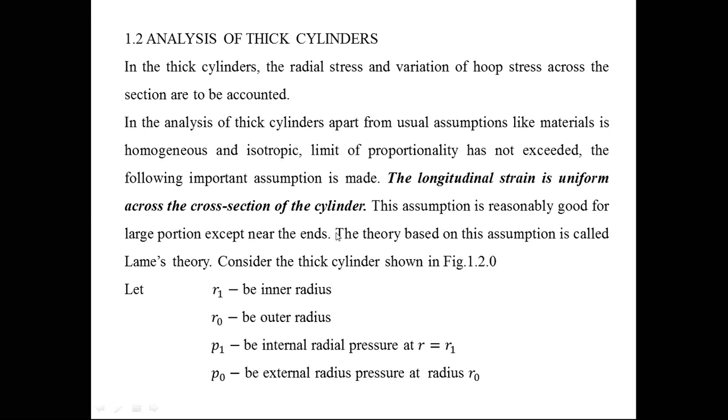This assumption is reasonably good for a large portion except near the ends, and the theory based on this assumption is called Lame's theory. So thick cylinders can be analyzed on the basis of Lame's theory. Simply remember that the analysis of thick cylinders is done by Lame's theory. So what is Lame's theory? The longitudinal strains are uniform across the cylinder. That's enough. Now consider the thick cylinder as shown in the figure.